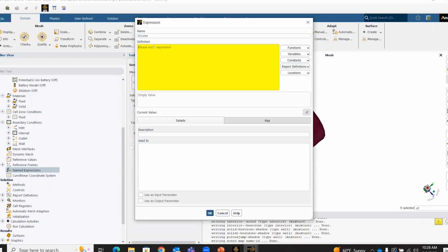Now, say for example, you're completely new to writing expressions, you don't know how to start. You can have some idea of how to use the functions and variables by looking at these drop-down menus over here. So I'm going to enter a conditional statement. I could go to conditional, and then click on if. And it gives me the overall syntax of an if statement. There is the condition first, and then what happens if the condition is met? What happens if the condition is not met? If you are completely brand new to writing expressions, I would say use these drop-down menus quite often.